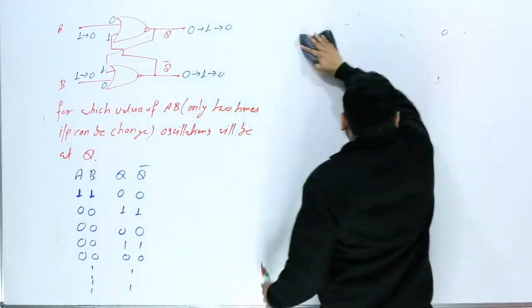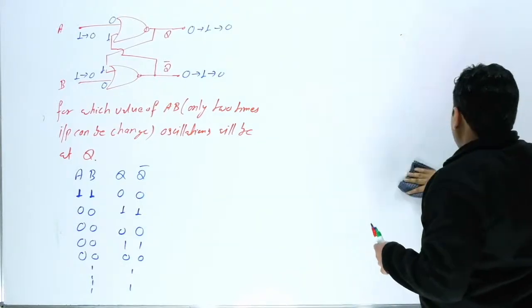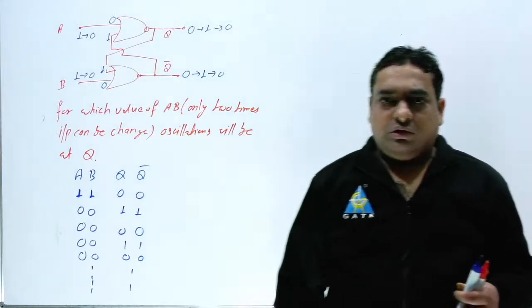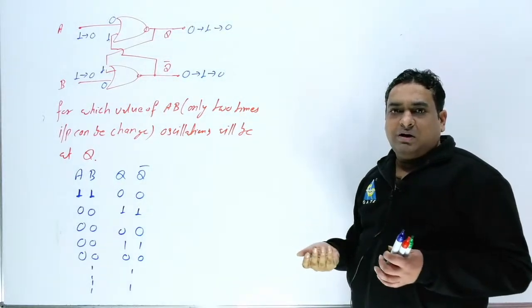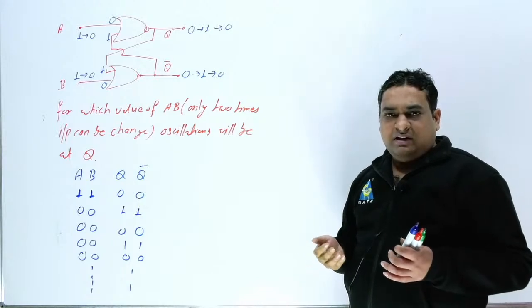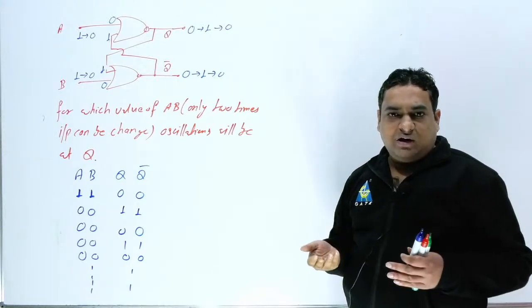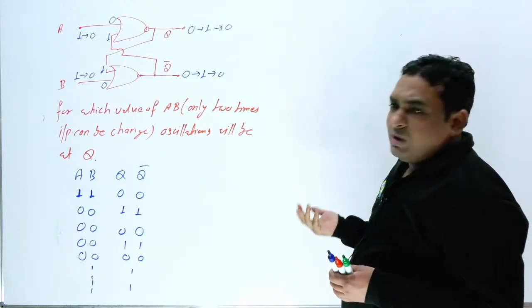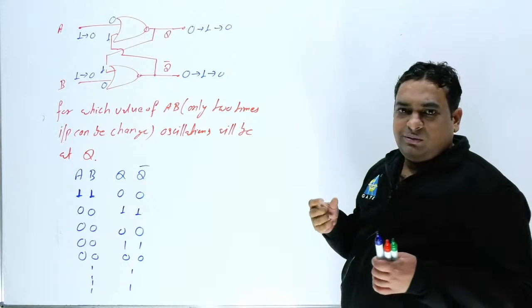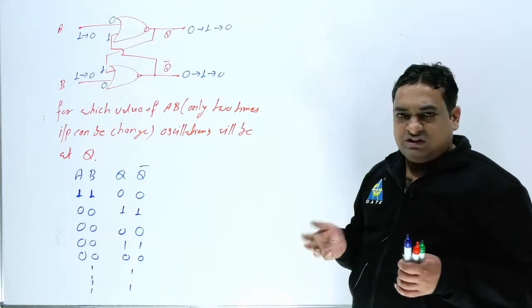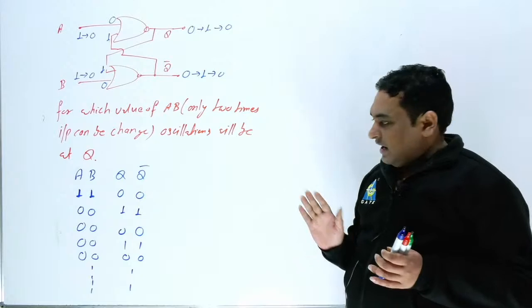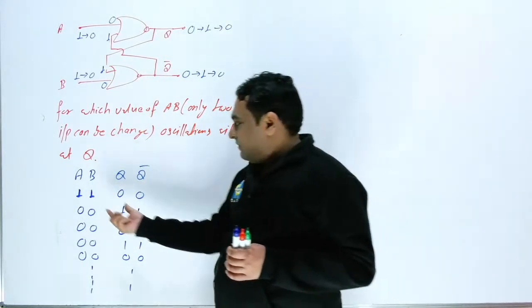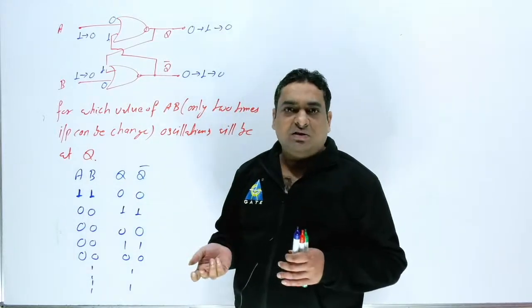Now the examiner can also give you a circuit of SR, positive or negative. You can assume negative level logic, or you can assume positive level logic. So two questions can be created, and two answers are possible: first an invalid state, and second no change. Sometimes you create the invalid state by 1 1, and sometimes by 0 0. This depends on the circuit.